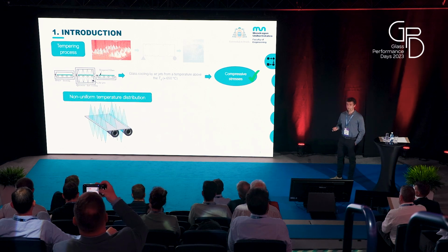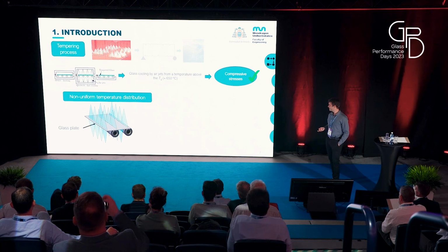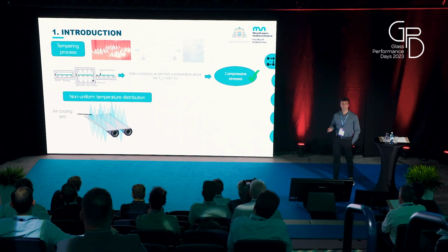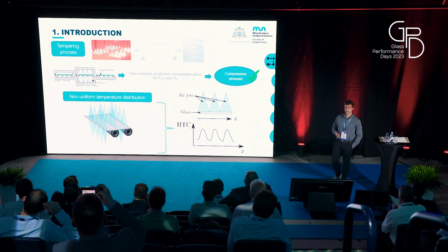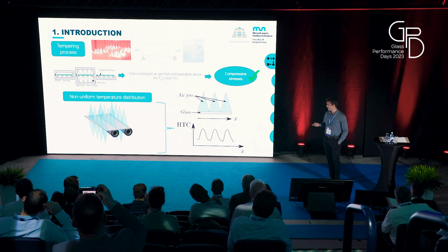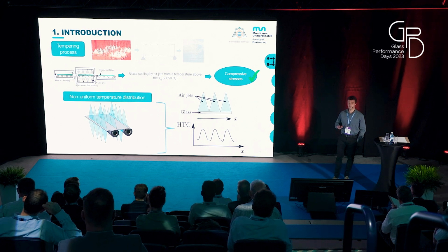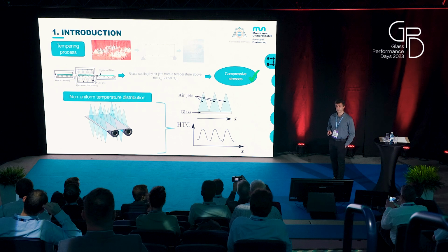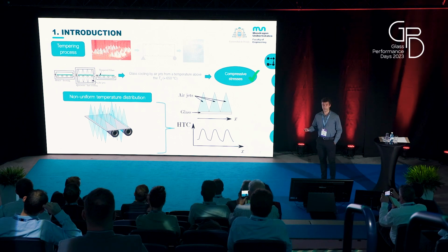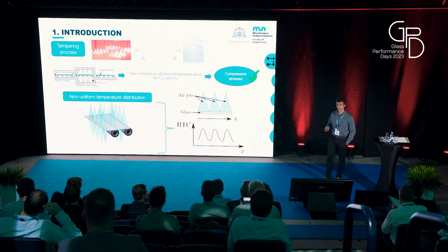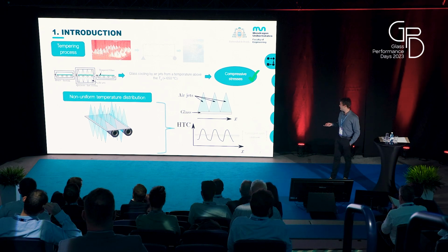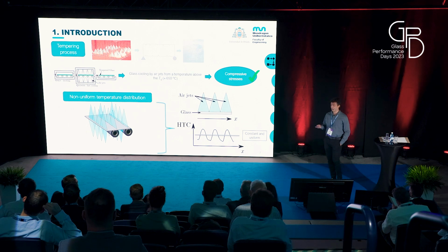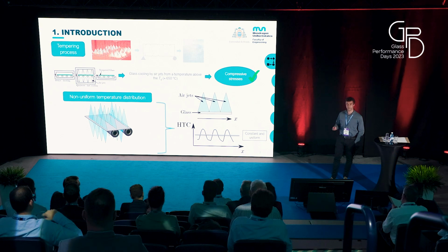Focusing on the industrial tempering process, we have a glass plate, some rollers, and air cooling jets. These air cooling jets lead to non-uniform heat extraction on the surface of glass, and as a result, we have a non-uniform heat transfer coefficient on these surfaces. This has a direct impact on the subsequent non-uniform residual stresses that are developed during the tempering process. During modeling, considering a constant and uniform heat transfer coefficient may impede the obtention of those non-uniform residual stresses during the calculations.